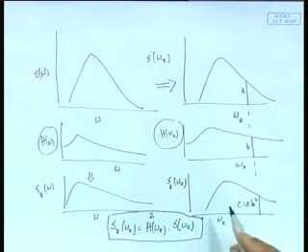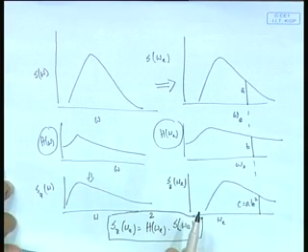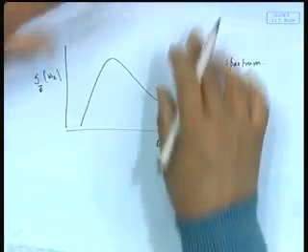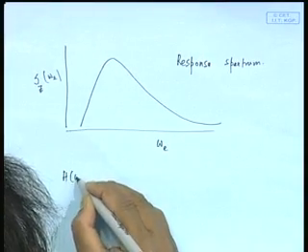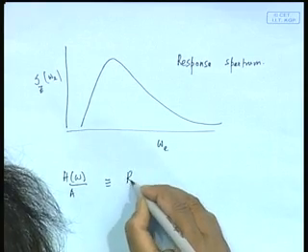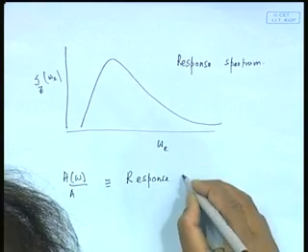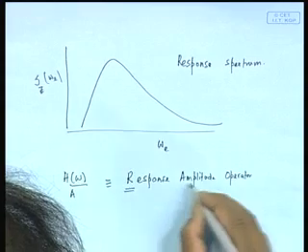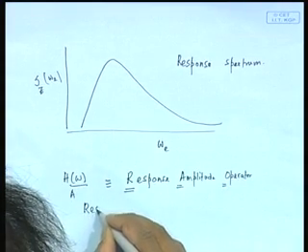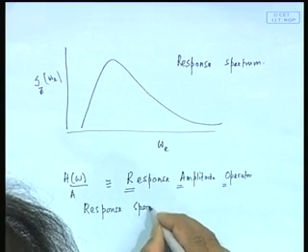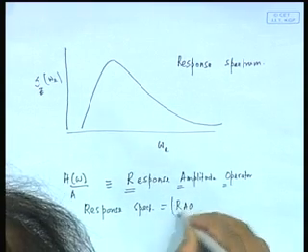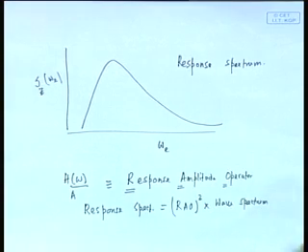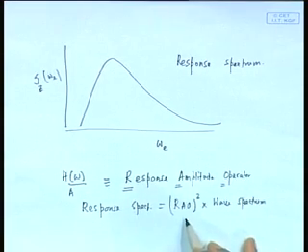See, this term h omega e square, look at that. In our subject, this is called RAO, response amplitude operator. So, you see, I will just write down this. See, the procedure is like that, no? The response spectrum is RAO square into wave spectrum.